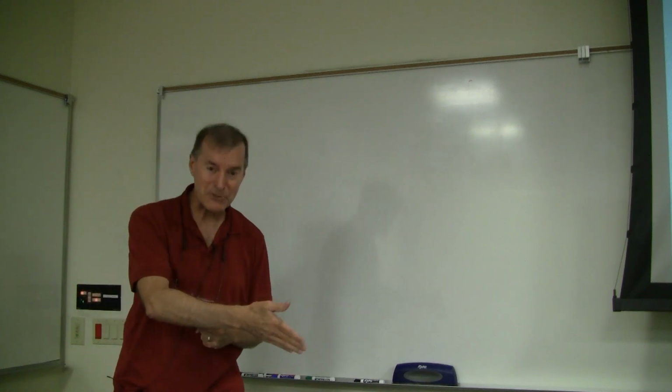And what we want to know is what the inputs must be in order to make that transition. So with an excitation table, what's given is Q at time t and Q at time t plus 1, and we want to know the input. A characteristic table is given the state and the input, what is Q at time t plus 1? You see how that works?